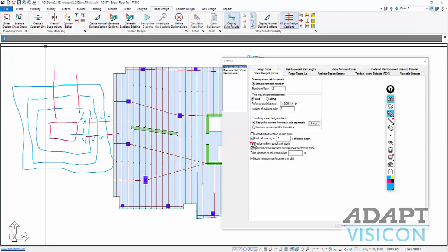It's just per computation. Well, if you have spacing that varies, let's say you have a rail that's 48 inches long, and you have spacing that varies from 2 to, let's say, 4 inches in the different zones along that rail path relative to these layers that we develop, the program, when we take the uniform spacing, is simply going to take the total distance from here to here. We'll call this L, length of the rail, L sub R, and it divides that length of rail by the minimum spacing. So we'll take that over 2, and that gives us uniform number of studs at the minimum spacing. So again, this is a conservative output.